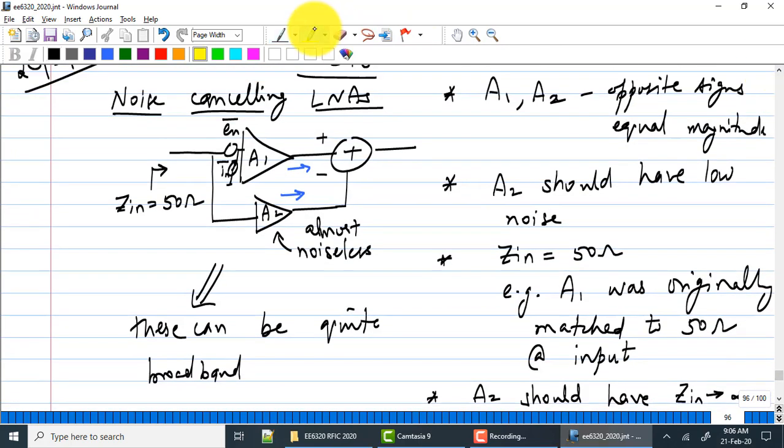So what we wanted to do was take an LNA, which may be noisy. There are several LNAs that are noisy, right? But broadband, right? The one LNA that we found which gave you really low noise figures had very narrow band operation. So you directly traded off bandwidth of operation versus noise figure. Okay. So what we thought was, let's take one of the noisy LNAs, which is hopefully already broadband, and try to do broadband noise cancellation through an auxiliary amplifier.